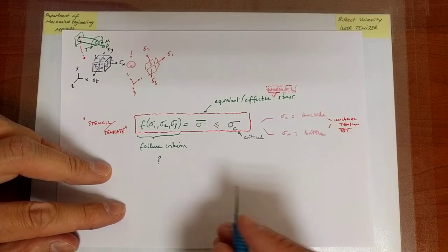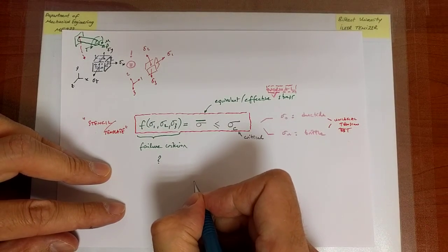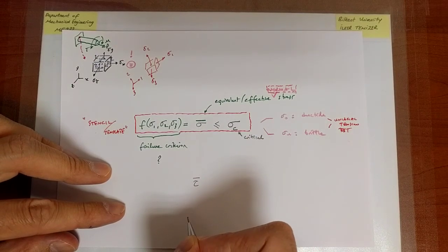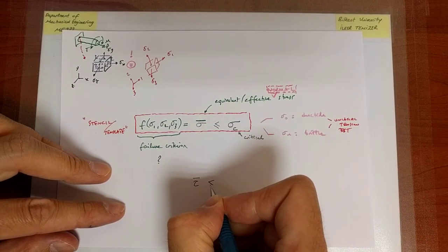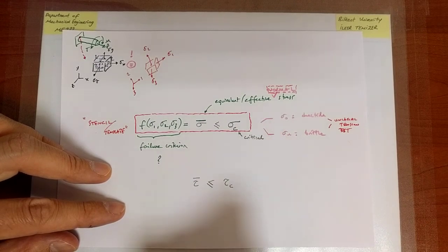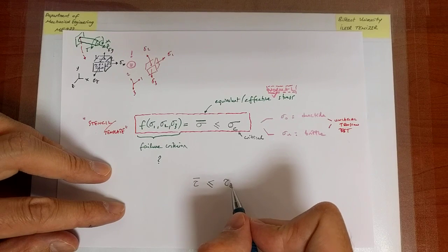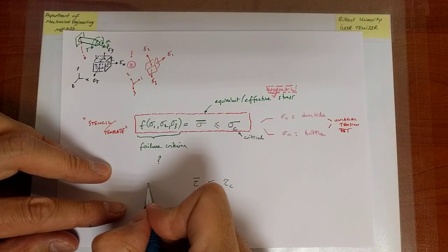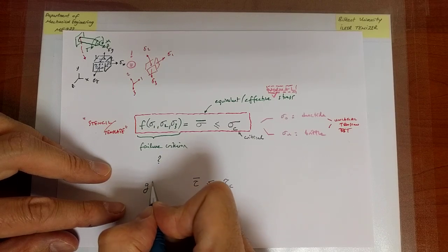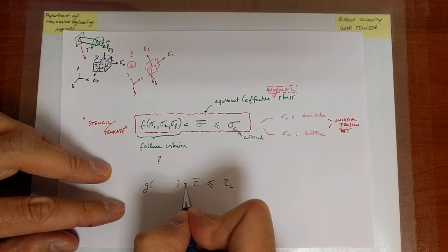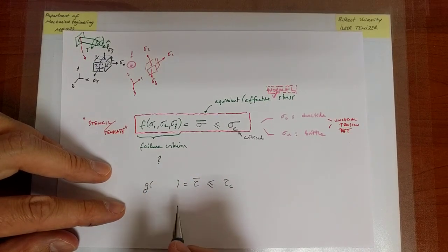What you may want to do is calculate an effective shear stress, and compare that against a critical value of the shear stress. And if you know the critical value, and if you have a function, let's call that another function g, that is able to give you what that value is, then you can predict whether failure occurs or not.